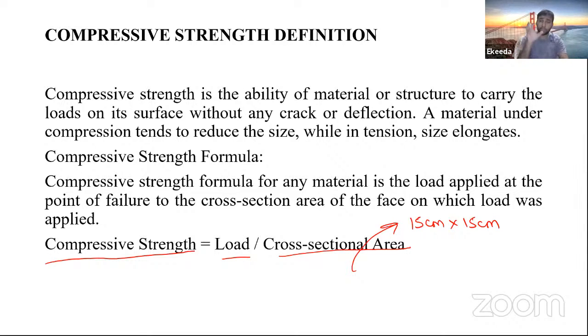Now that is one of the basic tests which is always performed before any batch of concrete. Before any batch of concrete, firstly we have to get the strength of that mix. First we have to determine the strength of that mix. If its strength corresponds to that of the concrete which is required, then we will take that proportion of cement, sand and coarse aggregate, and we will prepare the concrete in large amount. But if it fails, then we will not take that proportion.